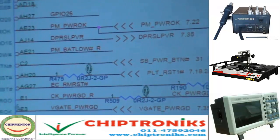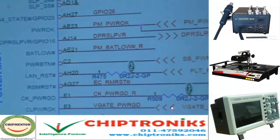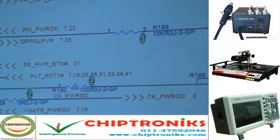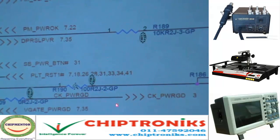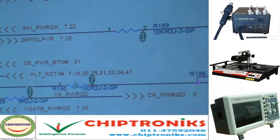Clock power good. This is a very important signal. When this signal is generated, the clock generator will become active and then generate the clock signal. Clock power good is going to page number 3. As I told, the first chip to start is IO, then ICH, GMCH, CPU, clock generator. This signal is given to the clock generator IC.